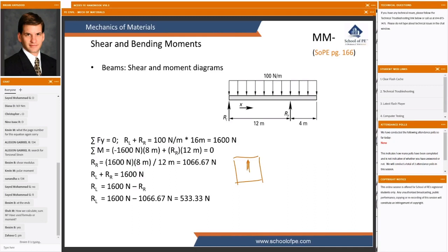Well, I mean, sort of, but even at the microscopic level, the head of that nail is going to have a little flat spot on the end of it from that beam. So every load, no matter how we support it, gets distributed across some amount of cross-sectional area. Or since we're doing 2D diagrams looking left to right, some amount of left to right width is present in every support.